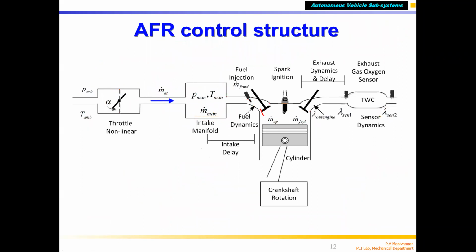So this gap, and the pressure inside the cylinder, PC, and P manifold, the difference in between decides, along with the temperature of the air inside the cylinder, the combustion chamber, how much air mass will enter into the combustion chamber when the vacuum is created. After combustion happens, the burned exhaust gas pushes the piston down. In the exhaust stroke, it will be thrown out. So finally, this is the three-way catalytic converter.